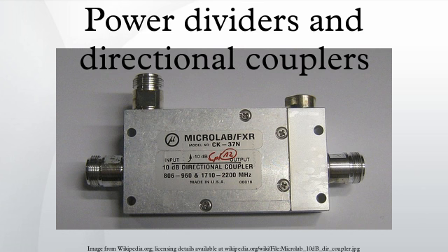The reason for this is that microstrip is not a homogeneous medium. There are two different mediums above and below the transmission strip. This leads to transmission modes other than the usual TEM mode found in conductive circuits. The propagation velocities of even and odd modes are different, leading to signal dispersion.